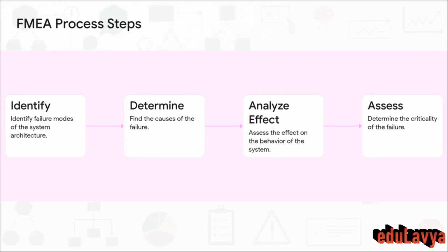The whole workflow operates like a methodical chain reaction. Step 1, identify the component's failure mode. Basically, how does it break? Step 2, determine the root cause. Why exactly did it break? Was it vibration, flooded ballast? Step 3, analyze the system effect. Does the entire network go down or just one single signal? And finally, Step 4, assess the criticality and redesign. We use this direct structural analysis to inform safety design changes, like adding necessary redundancies so the system fails safe.